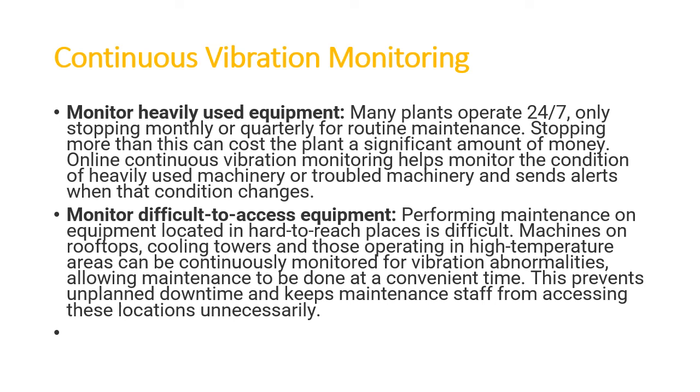The techniques we have discussed till now are not continuous vibration monitoring. We are monitoring the vibration maybe once a week, once a month, or once in 6 months, depending on the criticality and the type of the machine or the type of fault that we're going to experience. But there are some machines where we need continuous vibration monitoring, because that component is very critical. It needs to run 24/7 to cater to the whole complex.